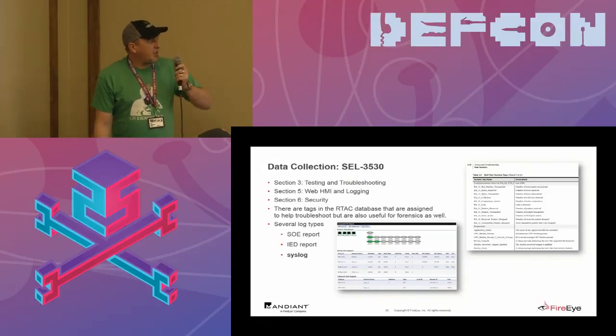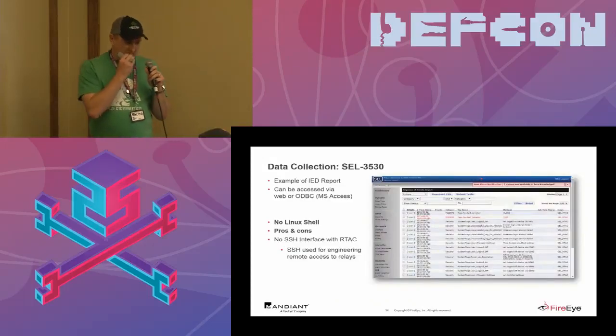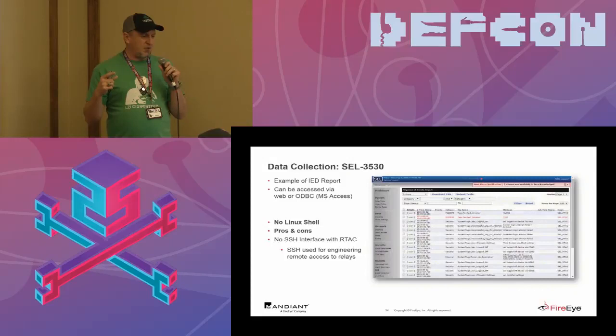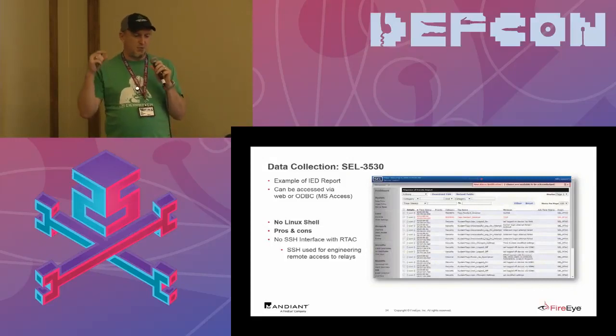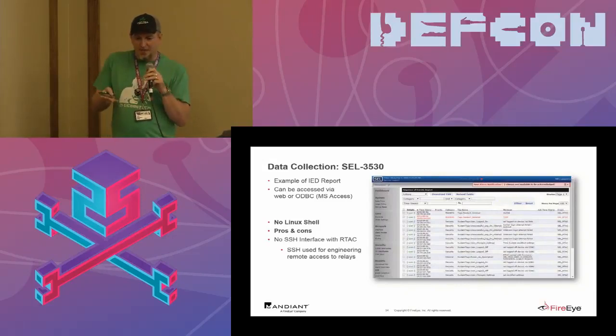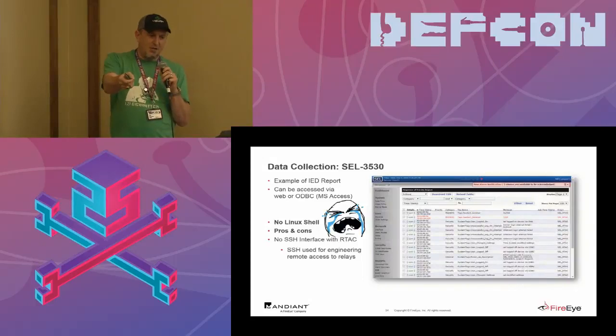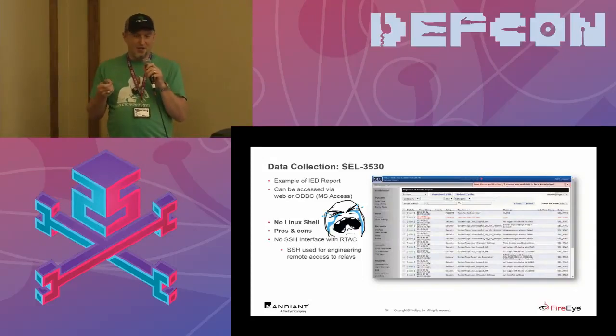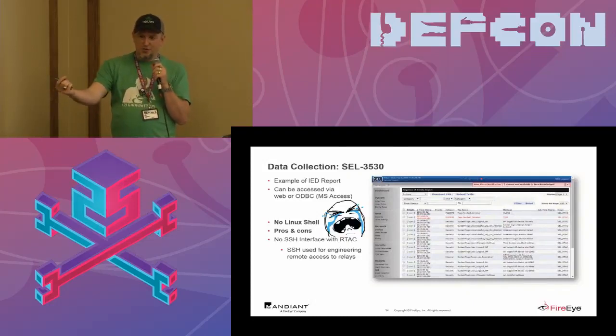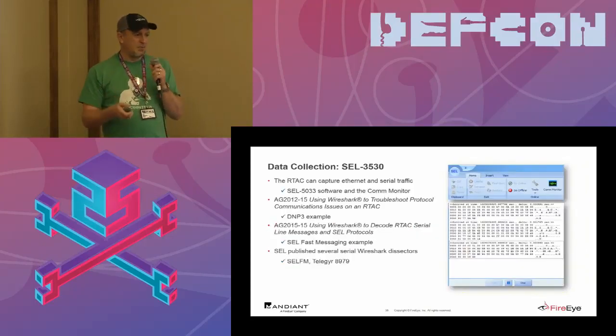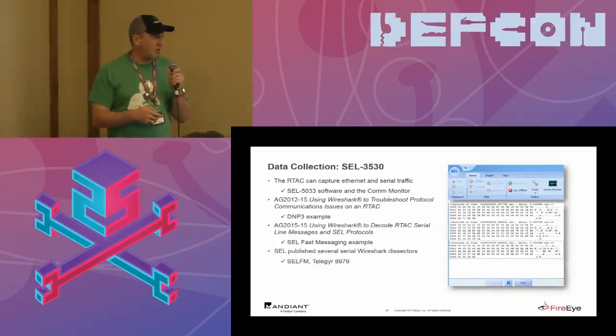So for data collection, you can get several different reports and logs, and especially syslog. A good friend of mine, Nathan, took syslog, but in the Schweitzer device you can make anything go into syslog. So he did all kinds of cool things to custom make syslog. If someone plugged in the Ethernet cable, he could write that to syslog. If you unplug it, it writes that to syslog. If a port is active, and he even tied a door switch on the cabinet into syslog. So there are all these really cool things you can do with this device.